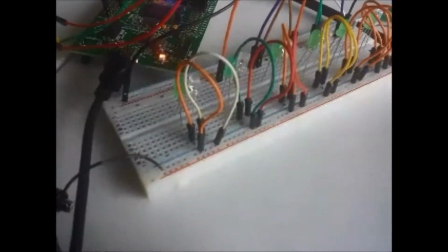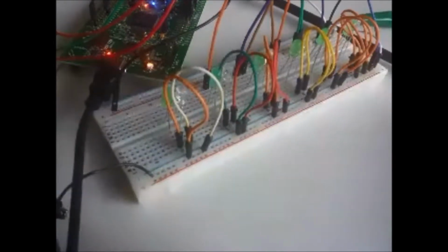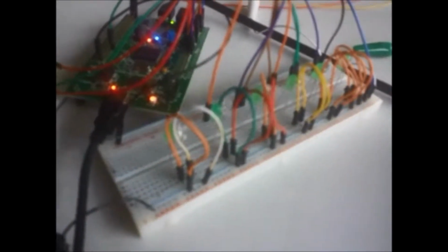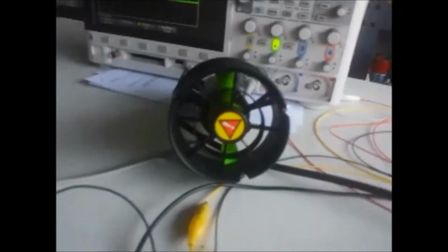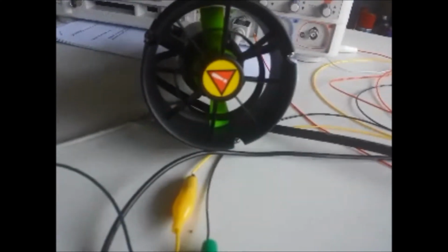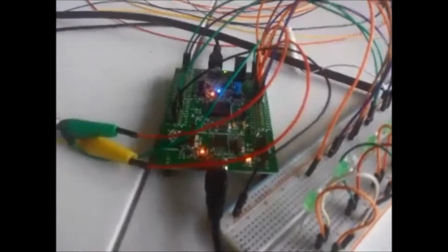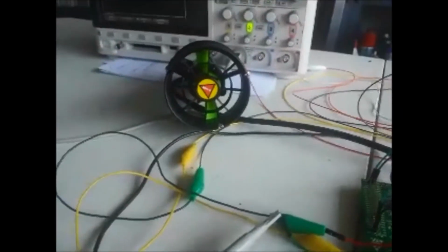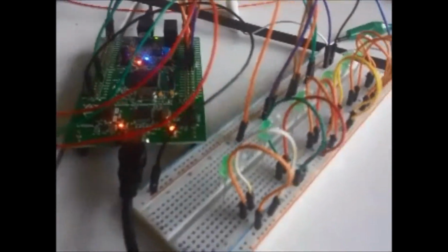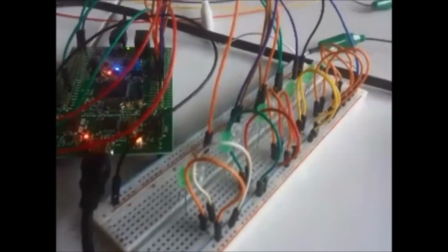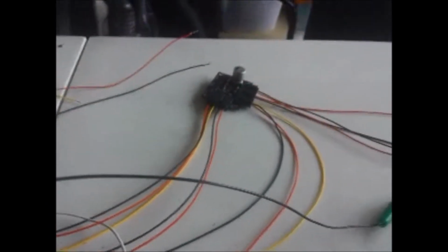The goal of this is not just to control lights, but to send this pulse width modulation to ultimately control a thruster, shown here. Of course, this microcontroller does not supply enough voltage to power this thing. So instead of sending the PWM to an LED, I am sending it to an amplifier, which is powered by this 24 volt Stark Power battery. It's 10 amp hour, and this will control the thruster.